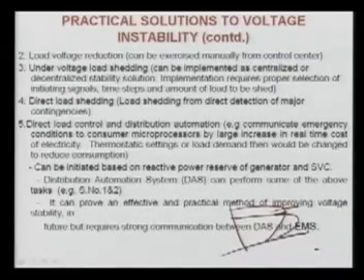In the generation end, I already discussed that we can improve the reactive power settings, using optimal settings of the reactive power outputs of generators along with FACTS controllers. Also we can put static var compensators or FACTS controllers in the transmission system, which will improve your voltage stability margin. But on the distribution side, you have to play with the loads as well as the transformer, that is the OLTC.